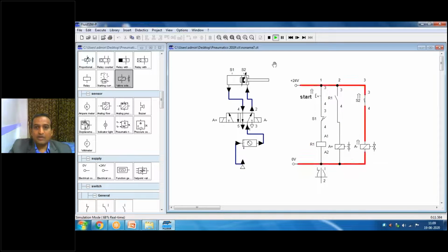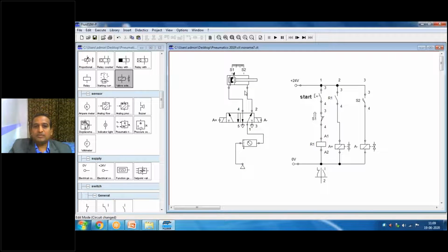Now next is very interesting, on delay timer. Suppose when the piston goes to S2, it has to stop for, say for example 10 seconds, because for drilling operation or reaming operation, some operation it has to stop, and after the completion of work automatically it has to go back to S1. And at S1 also you can give an on delay timer, because the second part you have to insert, so that you can use a timer on both sides or only one side.